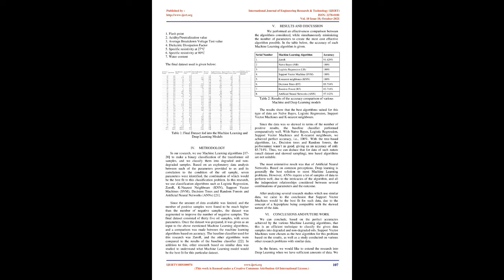Furan analysis. Furan analysis gives us an idea of the condition of the paper insulation by testing an oil sample. As time goes by, cellulose insulating material experiences degradation. In this process, an aromatic chemical compound is produced, which is known as furan. Testing is typically performed for the 5 main furans, as follows. The results of the furan test are used to determine an average expected degree of polymerization for the insulating paper, which is in turn used to estimate the percentage of solid insulation life remaining inside the transformer.